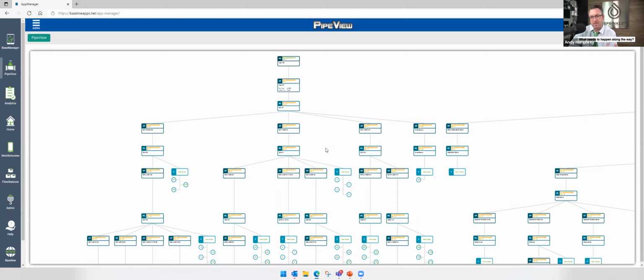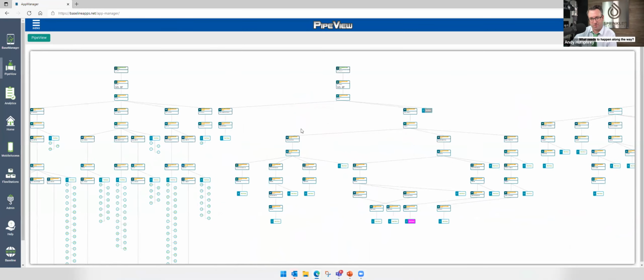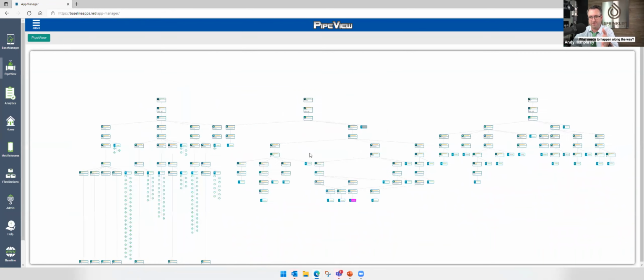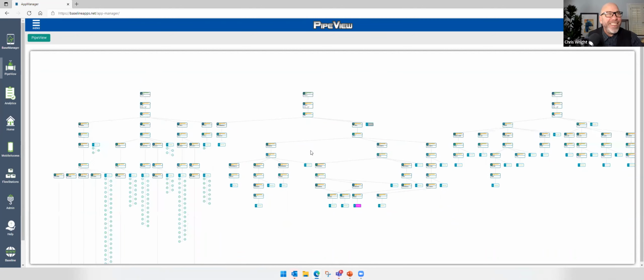And we know that most systems are one water source, so it just looks very linear. Water source, control point, main line, zones, just boom, linearly. This is a complex system because we're, I guess, trying to impress you and show you the capability. But I would encourage you to log into PipeView and check out your system, see if it's configured correctly. Absolutely. A lot of times you'll see, oh, I guess we missed setting up the master valve. Or man, I'm not seeing my flow sensor. Shoot, I didn't configure that correctly.